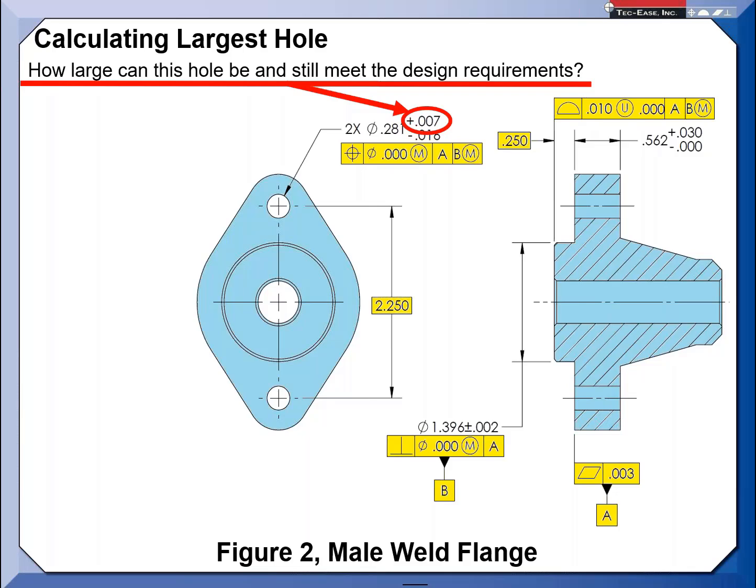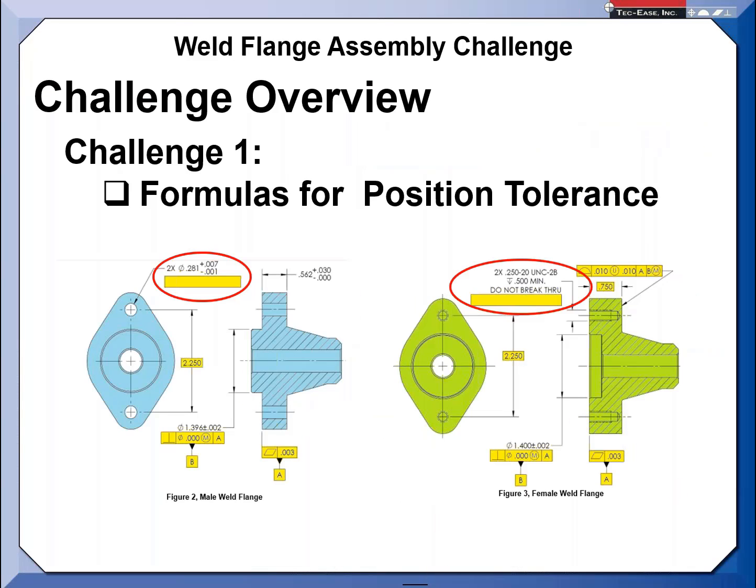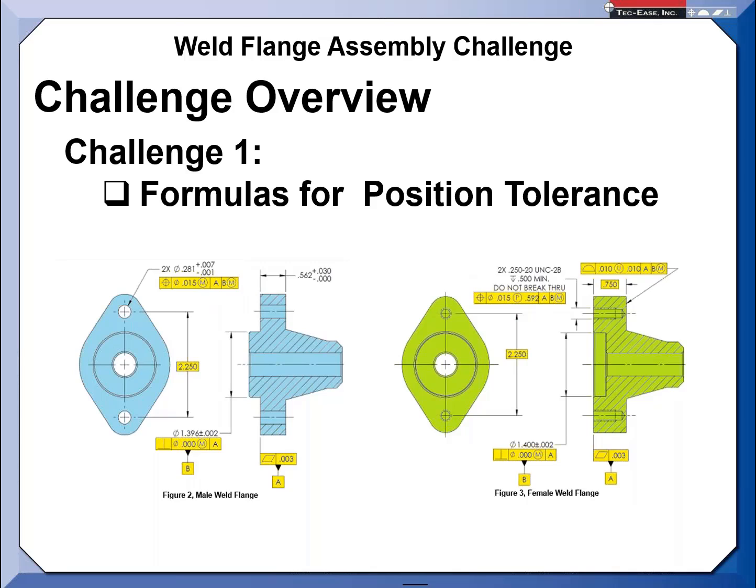Yeah, if you take a look at the 250-20 thread tolerance block, you have a positional tolerance, I believe it's on the next slide again. You see, you have 0.015 and then projected tolerance. You don't have M, although the standard shows M. If you take a look at the ASME Y14.5 standard, it does provide maximum material for the threaded features. So my question is, what is correct?